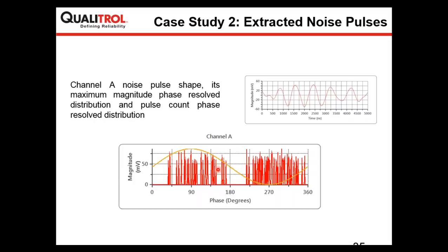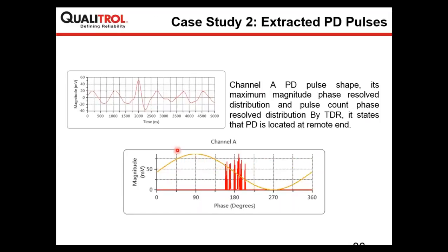So this was one of the activities, which was a noise activity in that data, and from the same data, this was the partial discharge pulse which was extracted by the software, and this was the phase resolved partial discharge activity.